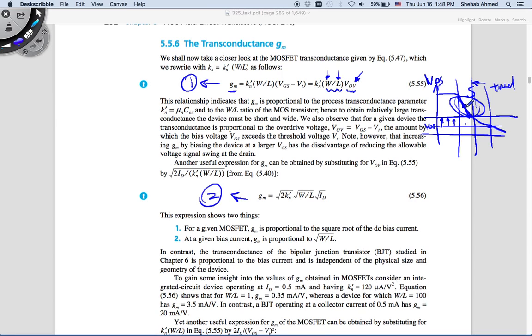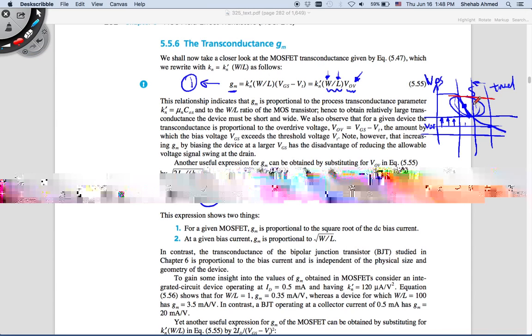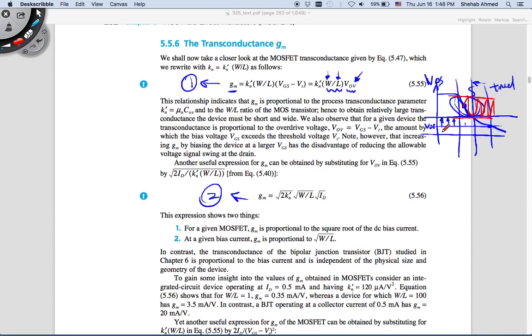If my operating point is limited to a small space, then also my signal swing is limited to a small space as well, right? So fine, this is a way to do it, but you will be limiting, for example, signal swing, and you will have to live with a wider device, which may be okay. What this says is that the gain is also controlled by your DC operating characteristics.